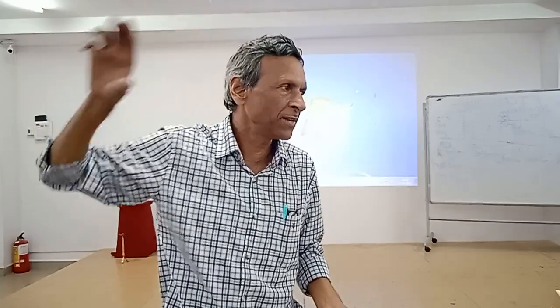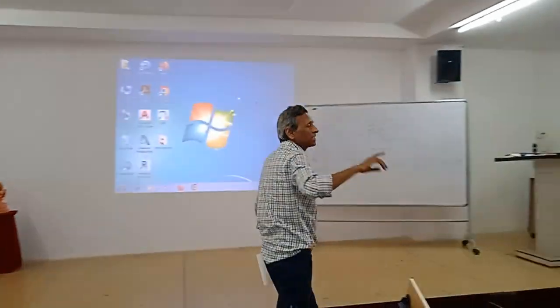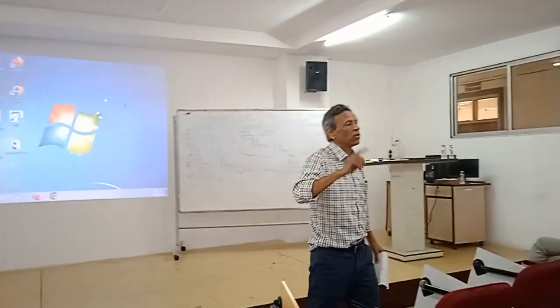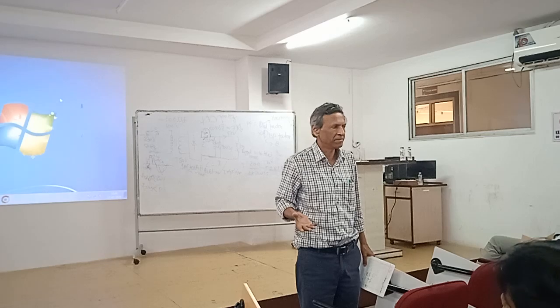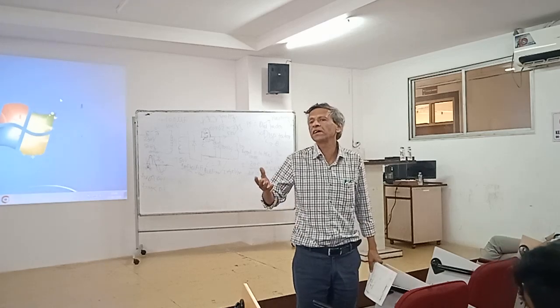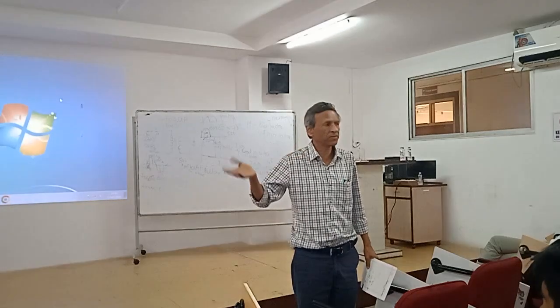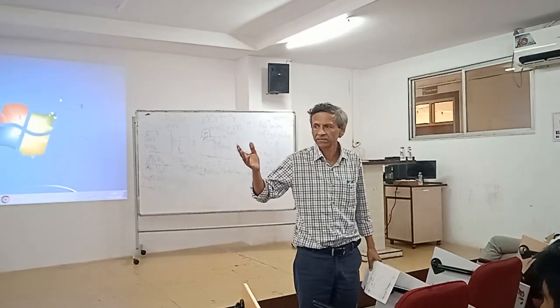If the waveform is symmetrical in both halves, it is called half wave symmetry. If the waveform is half wave symmetrical, then it is going to generate only odd harmonics, not even. That you can prove in MATLAB. That's why we always speak about first, third, fifth harmonics.